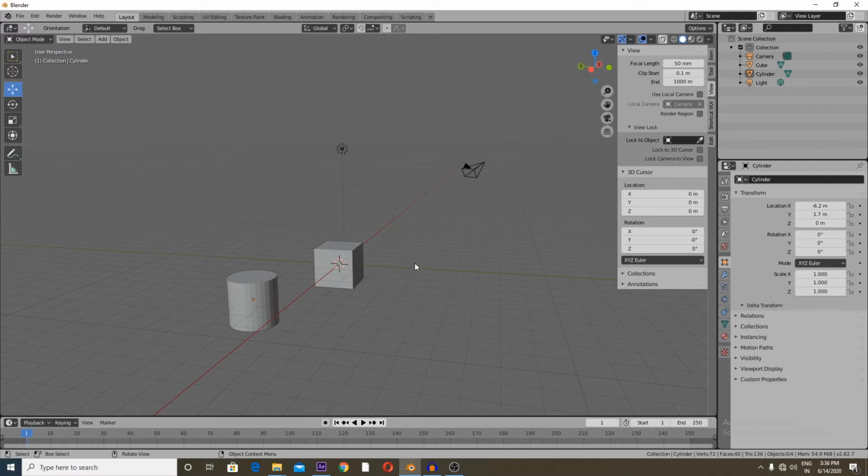However, there is a very important tab at your bottom that is called the timeline. You can anytime play your animation by just clicking here, and you see a time slider running. You can anytime zoom in or zoom out by scrolling up and down, or by dragging with the middle mouse button, or you can change the start and the end of your animation.